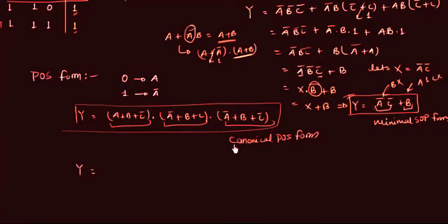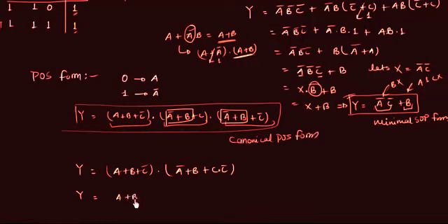And you can see in the last two terms, A complement or B is common. So I will take it common. And we have A complement or B or C and C complement. This is from the distributive law. C and C complement is equal to 0. So we are left with A or B or C complement. And if this is X, so we have X or 0 and X or 0 is equal to X. So I have written A complement or a B.